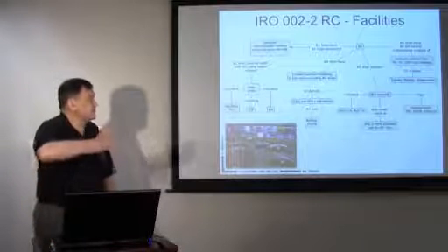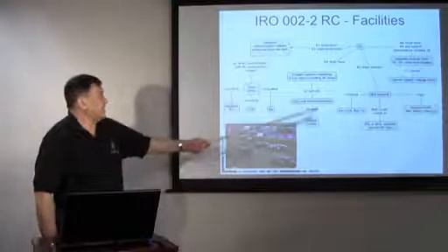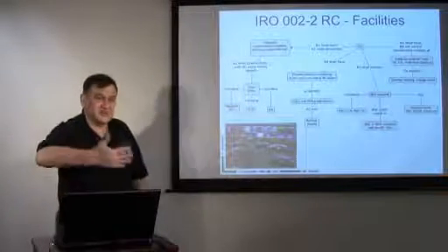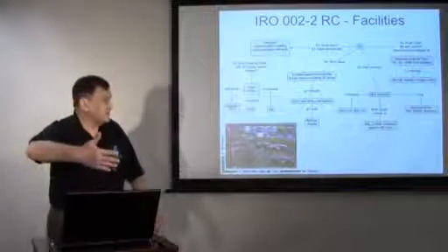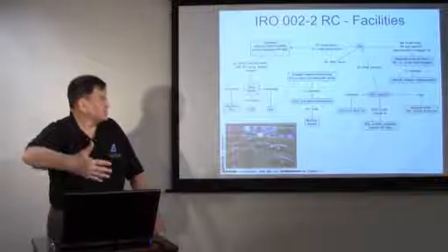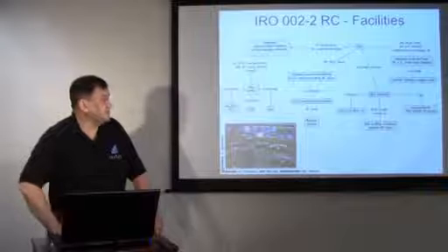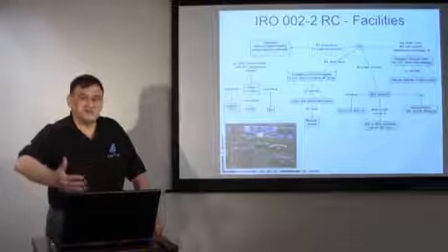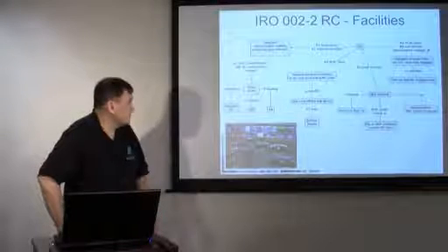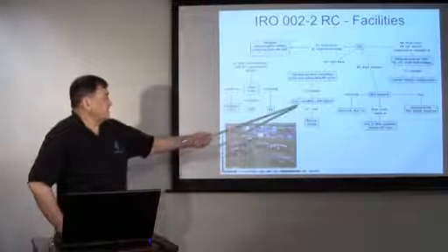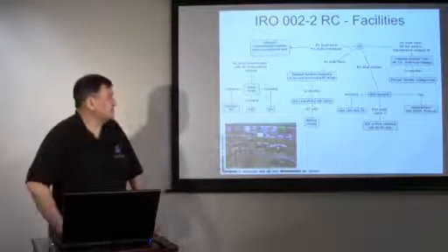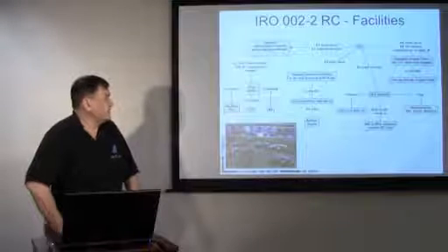But basically, from the reliability point of view, they shall have real-time monitoring of their own area as well as their neighboring areas. It's very important. On a large interconnection, we can have the Midwest ISO connected in with PJM. It's important that they be able to jointly share studies where an outage in one region may have an impact on another. So they will identify the SOLs and IROLs with alarms. So there will be messages coming to the operators when there are violations.